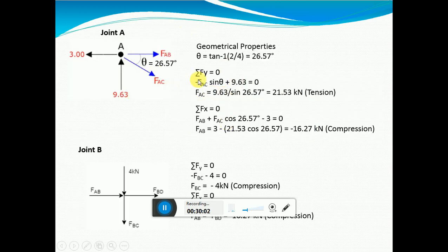For this joint A, it is solved. Move to joint B. Instead of the arrow mark moving outside, since I have got this as negative, I'll put it as moving in, on the compression side. Then in joint B, what other forces are acting?